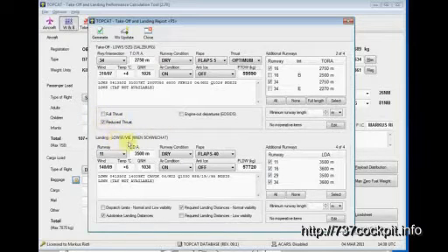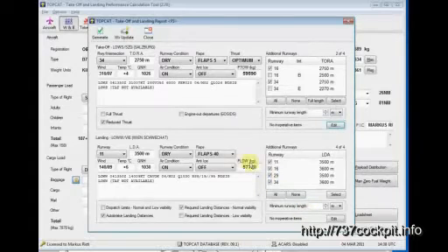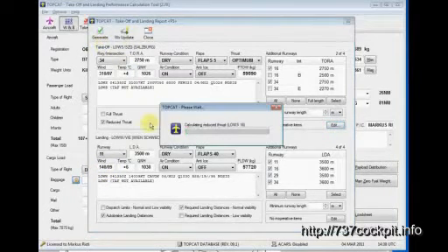For takeoff, we check the reduced thrust. And for landing, we will do a flaps 40 landing, anti-ice is off, and the air condition is on, runway condition is dry. We have winds in Vienna from 140 degrees at 09 knots. So maybe runway 16. If we press generate, it takes some time to generate our takeoff report.